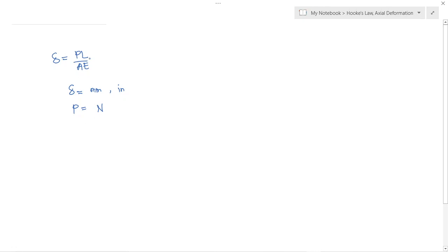So, if you are going to substitute values or magnitudes dito sa equation, make sure P is in Newton, L is in mm also. So, express length in millimeter, and then area is in square millimeter, kasi usually, maliliit lang din naman yung cross-sectional area, measured in square millimeter.